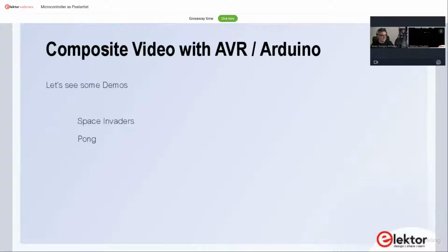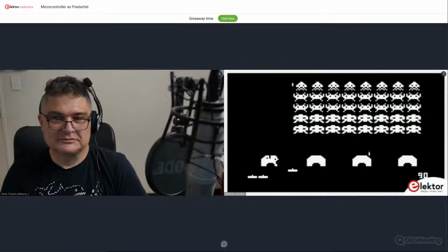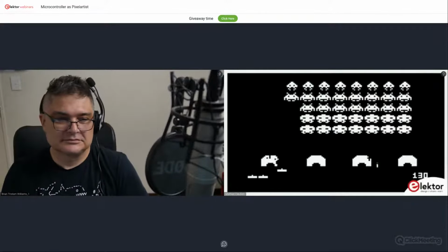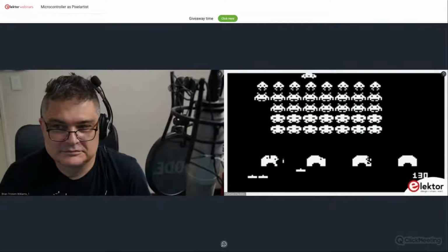this is quite nice. So you already talked about the Space Invaders, and that's what we also have here, a fully working Space Invaders. And yeah, controlling that and not seeing where I hit. That's so amazing. This game is fully running on the AVR, just the two resistors and the joystick, of course. You need to control your chip a little bit, and that's just doable with the TV out library. So not much trickery, looks really nice, nicely animated. You have a set of a few sprites that you write into the RAM, just pixel on, pixel off. I think that's a cool one.